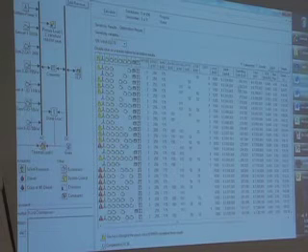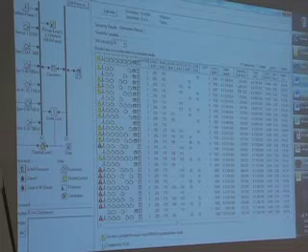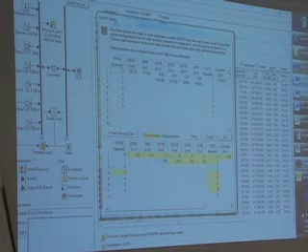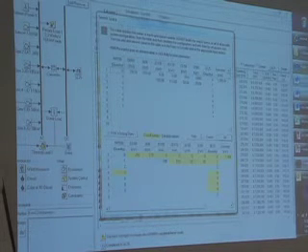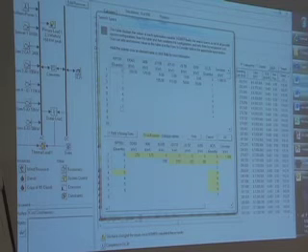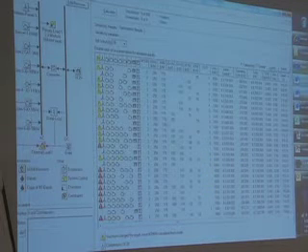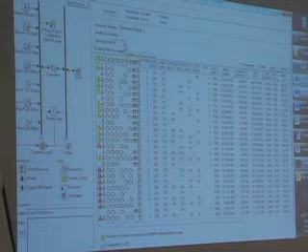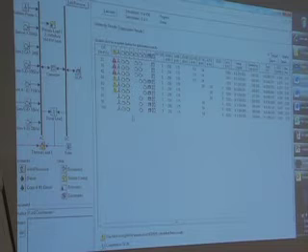So when I get a file like this, one of the first things I do is look at the search space here to see, well, what are we looking at? What's the question that's trying to be answered? And in this case, it's how many wind turbines and how many flywheels, and whether or not it makes sense to put in smaller generators. And we're doing a sensitivity on the operating reserve. So let's look at that first.